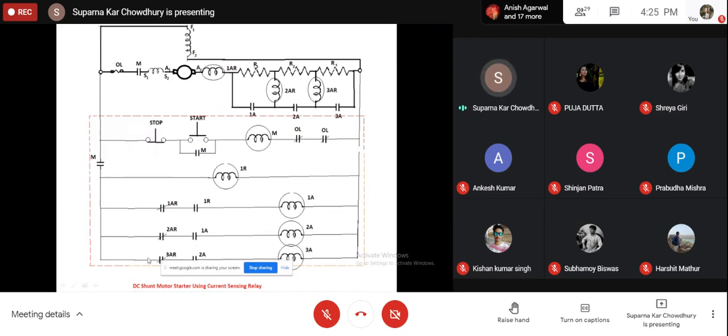In this circuit, this is open and this will close because 2A has closed. Again, this current inrush will gradually die down, and when it falls below a certain value, relay 3AR will drop off.